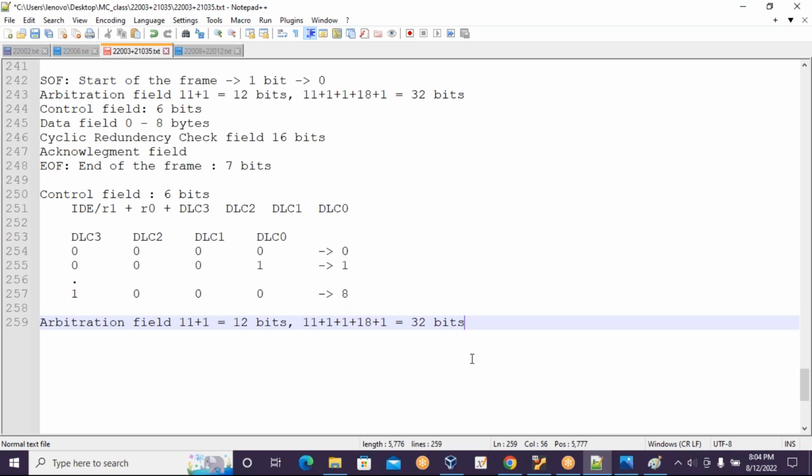So what type of protocol is this? Is this a synchronous protocol or an asynchronous protocol? Yes, this is an asynchronous protocol. Remember, this is an asynchronous protocol. That means there is no clock line. Because there is no clock line present in the communication, we have to trigger some signal in order to get the attention of the receiver.